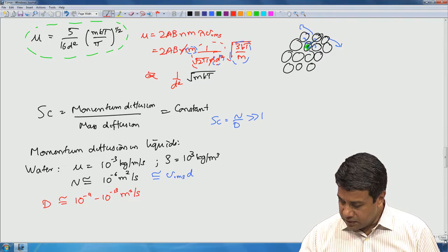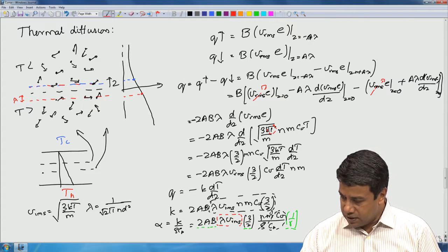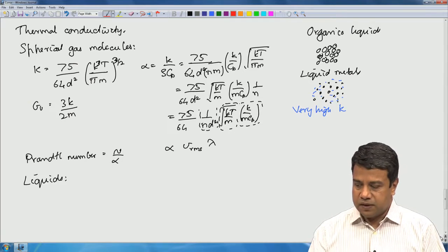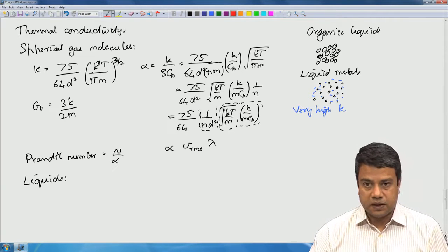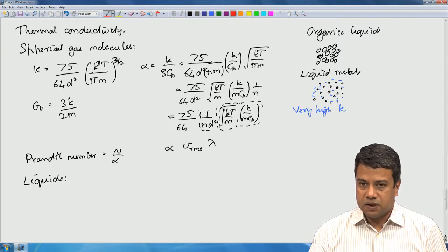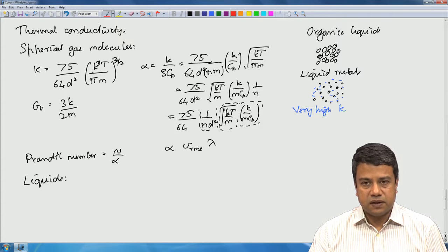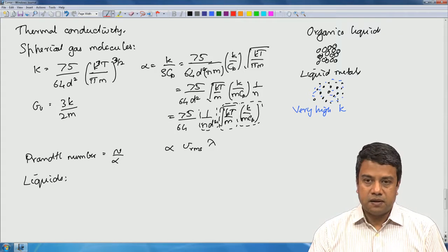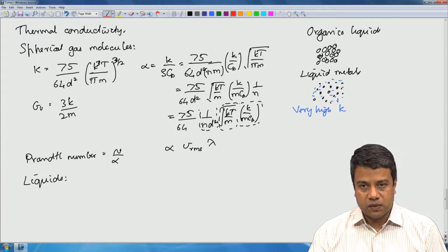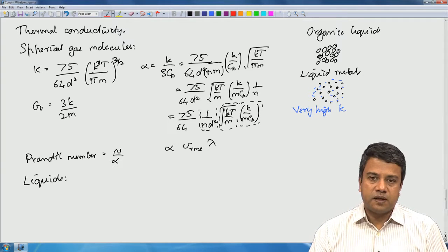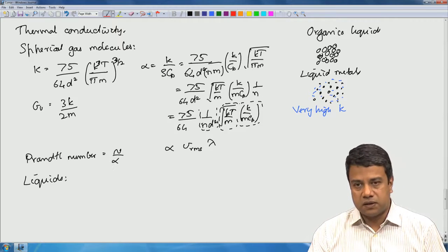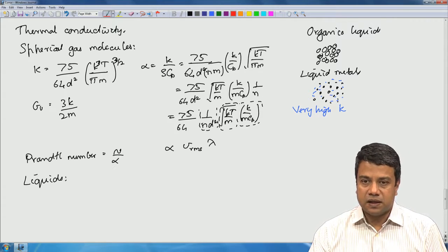The thermal diffusivity in liquids depends upon the mechanism. As I had tried to explain in the last lecture, the thermal diffusion coefficient depends upon how energy is transported. If it is due to intermolecular forces, you get a relatively small thermal diffusion coefficient, of the order of 10 power minus 7, whereas in special situations like liquid metals, energy could be transported through the electron gas around the nuclei, and that results in very fast transport. So, in summary, that is diffusion.